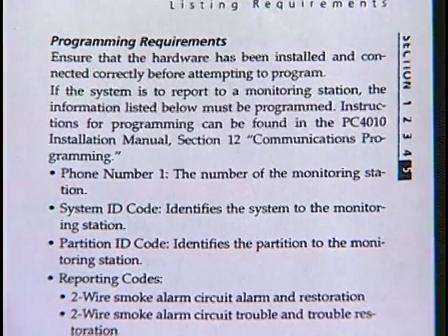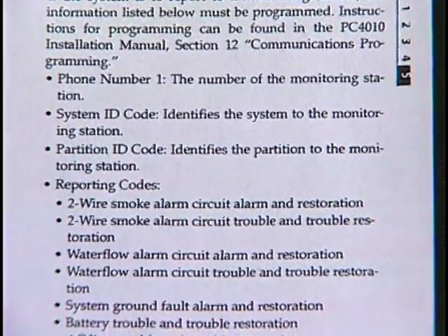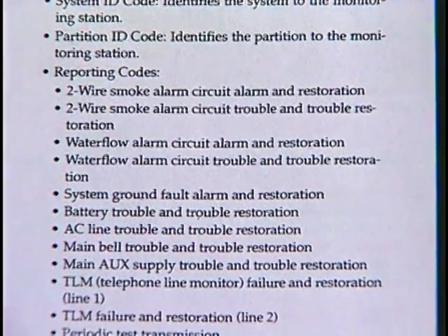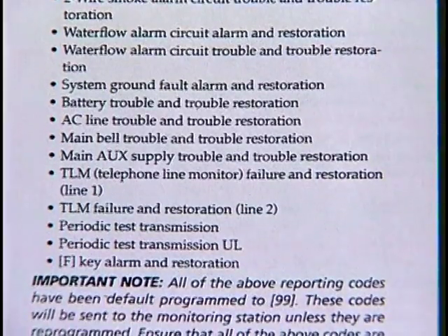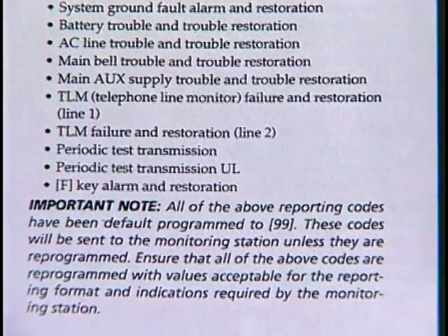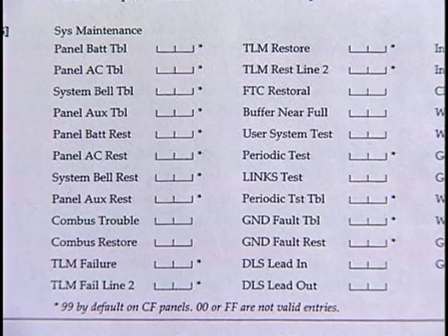There are a number of hard-coded programming changes in the PC4020CF to ensure that it complies with UL and NFPA regulations. These include reporting codes and operational functions. The reporting codes that must be programmed are indicated in the programming worksheets with asterisks.